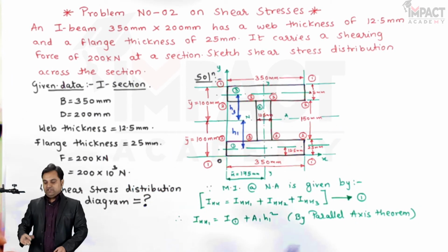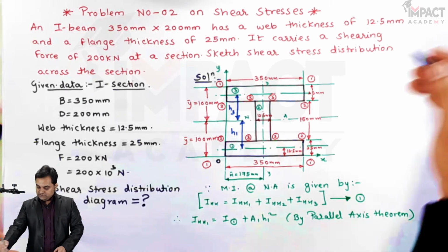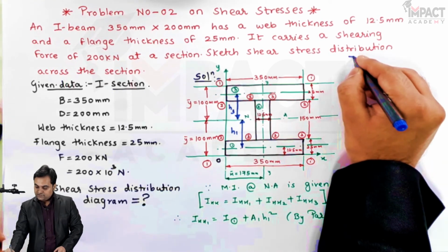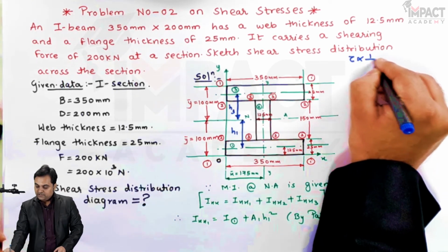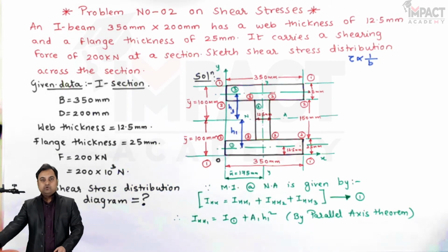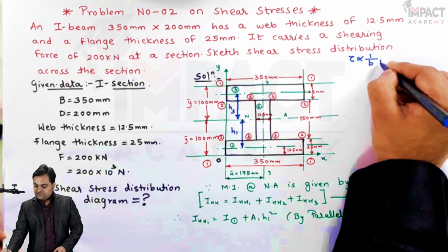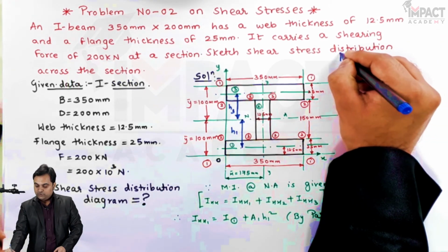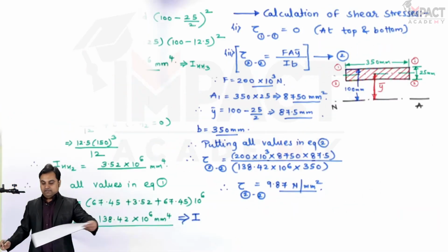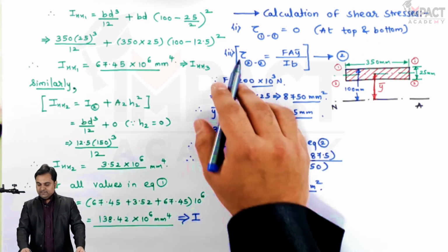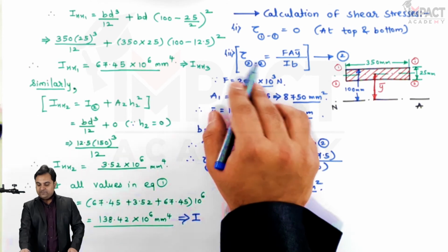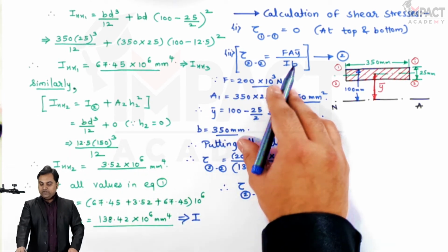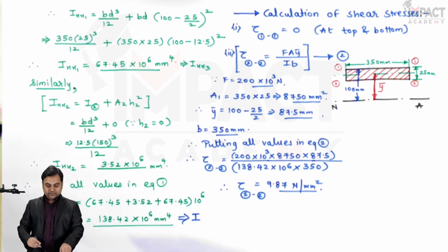So whenever we see in case of shear stress, the relation of shear stress and width, they are inversely proportional. So whenever width decreases suddenly, shear stress should increase suddenly. Like I can say that even in this formula we can see that tau is inversely proportional to B. So when we decrease B, tau is going to increase suddenly.